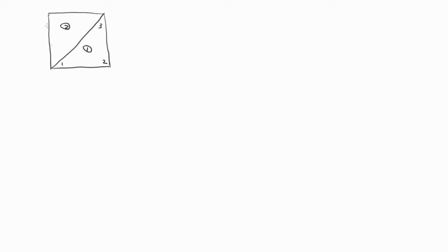And of course, we know that node numbering matters. So if I want element 1 and element 2 to have the same element stiffness matrices, I can't just number them arbitrarily locally. I have to number them in a smart way, and the way to do it would be to number it 1, 2, 3. In other words, I can't just start in the lower left corner and go around, or I'll have a different stiffness matrix if I do that, right? So let's look at how we'd assemble this one right here.